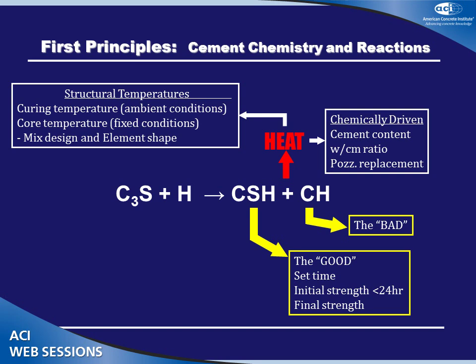This heat, I want to highlight for you here. One is chemically driven. The cement content, the water-cement ratio, pozzolanic replacement, all contribute to that. The other part of this is the structural temperatures. Notice a couple of things here, the curing temperatures. The curing temperature is largely controlled by ambient conditions.